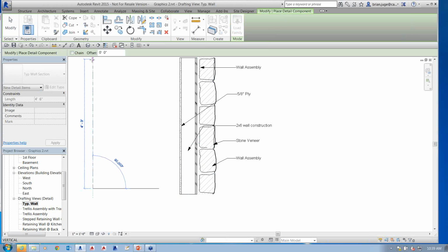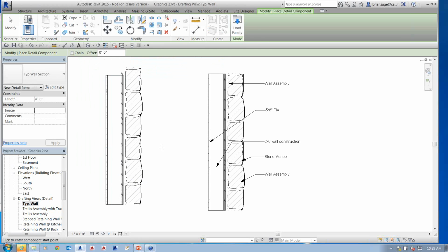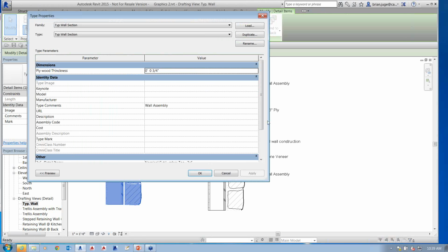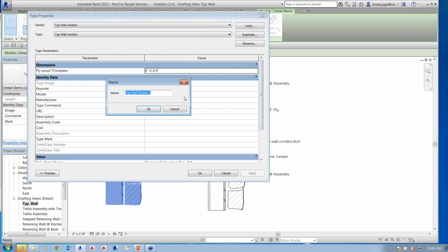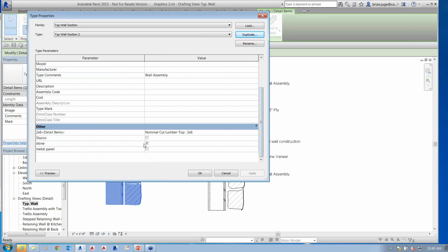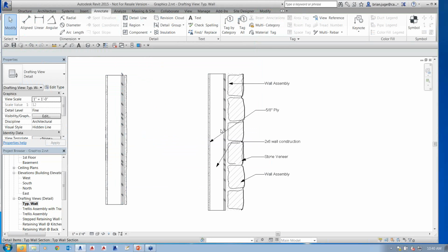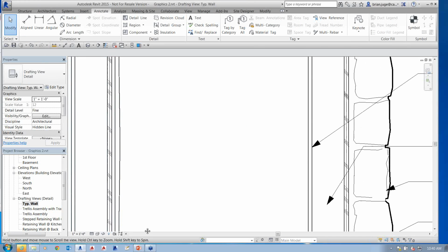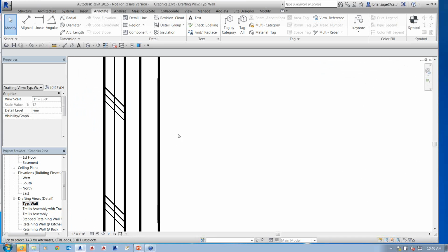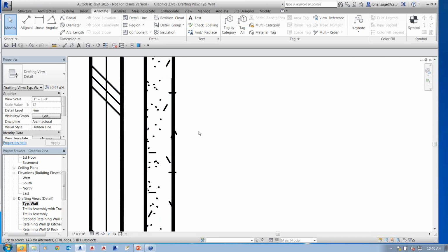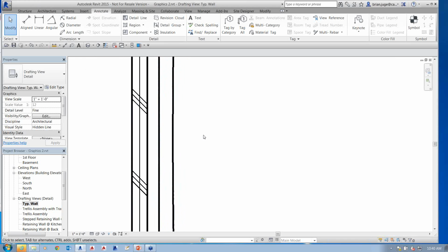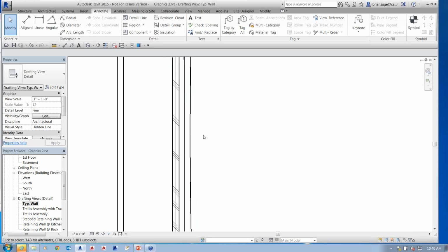So for this particular wall, all it is is one line that I draw, and I could type in here to make sure it's straight. And as I draw that, it's going to draw that wall, and it has all the different parts. Well, you probably didn't know this, but if I come inside here, I've got this one showing stone, but I'm going to go in here and show stucco. And then this one's got stucco, that one's got stone, and we can see we have that in here. And I've got this nice curvy little line in here showing the outside of the stucco and the stucco band. And inside here, if we look a little bit more, I've got kind of a sand hatch going halfway through and then getting into more of a gypsum hatch on the outside. So it gives me kind of a different effect inside here.